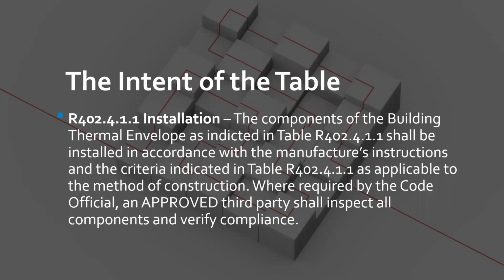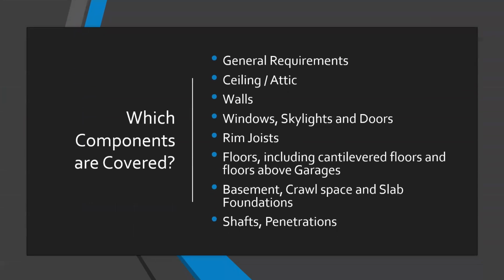Some third-party energy verifiers take it to the next level, which is kind of what we did. You include photos of each of these components, proving that you were, A, on site, and B, proving that it was compliant or it needs to be fixed. The photos can be geo-stamped with location and date and recorded in the house or building file independently. And you can also use it to show any failing items, even annotate those, circle them, and send them to the contractor or the builder for it to be corrected.